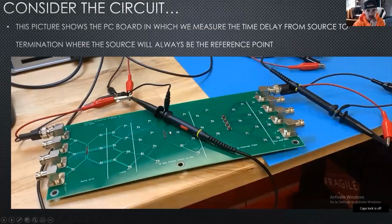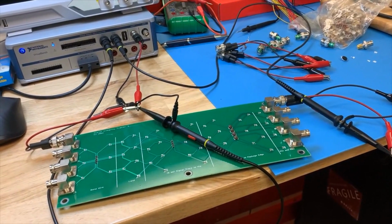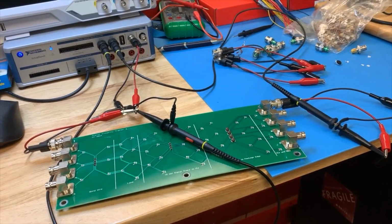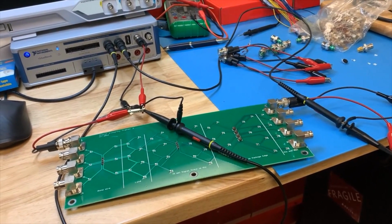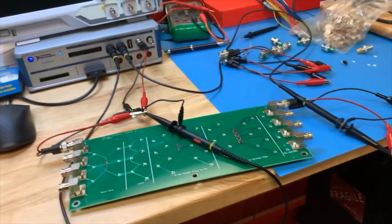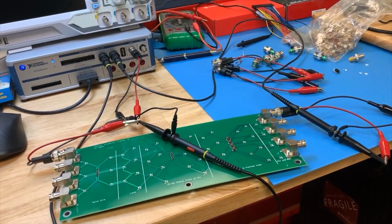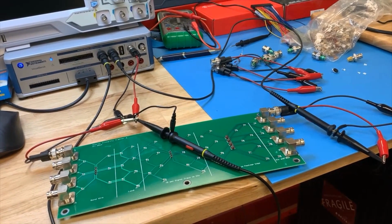This picture shows the PC board in which we measure the time delay from source to termination, where the source will always be the reference point. Now we are going to measure the time delay at line 1 of the circuit. So this is our current configuration for that setup. We have an oscilloscope at the source, and then we have an oscilloscope at the end, and then we can compare the two and measure the time delay of the line.